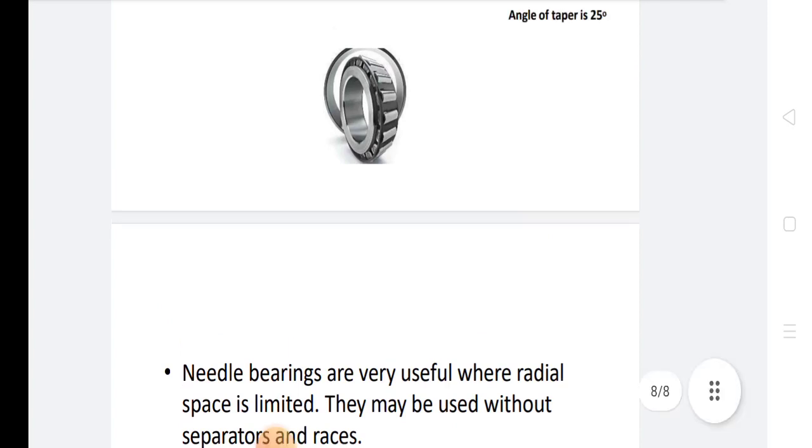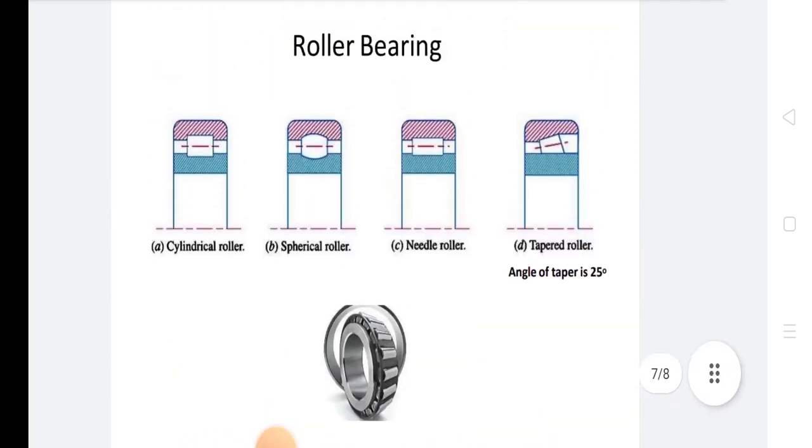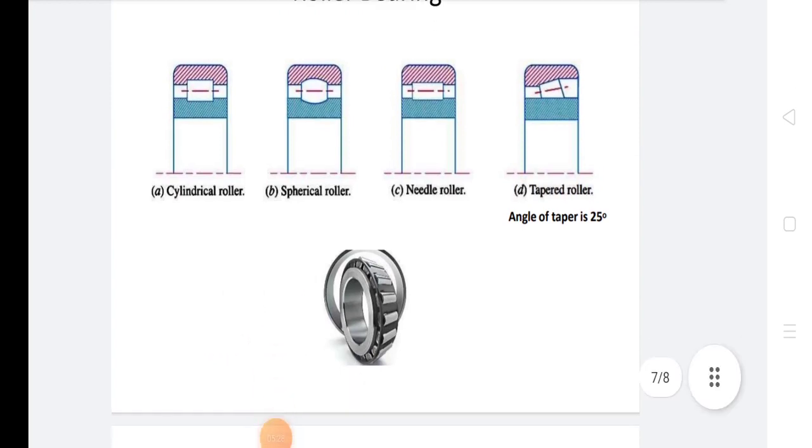Now we discuss bearing life for industrial applications. First, machines used for short periods or intermittently, whose breakdown would not have serious consequence: life is 4000 to 8000 hours. Machines working intermittently and whose breakdown would have serious consequence: life is 8000 to 12000.